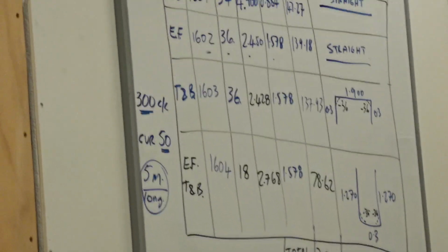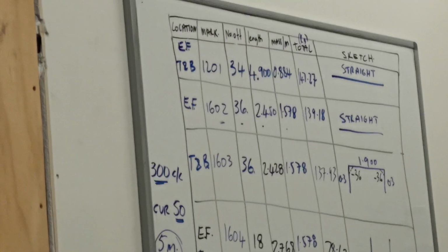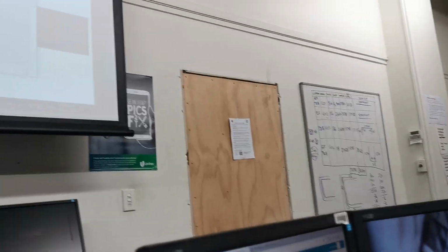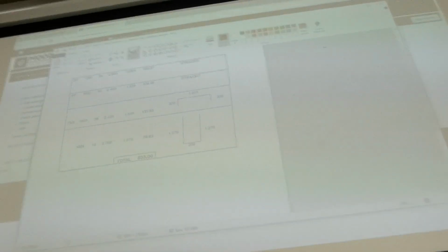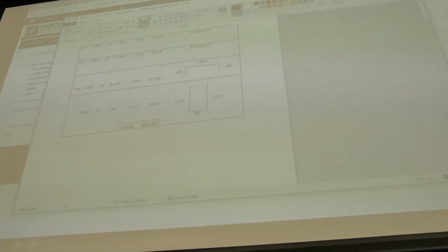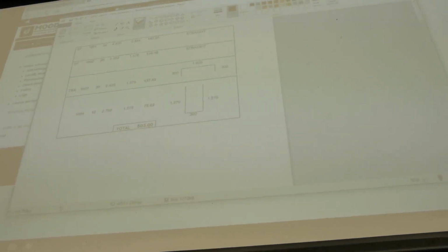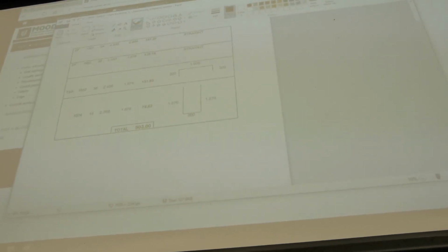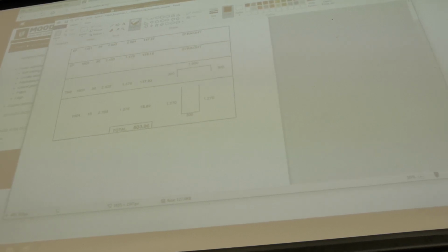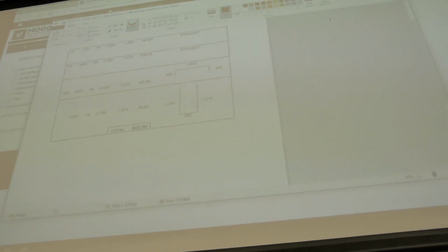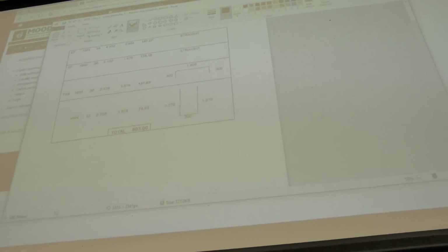When we label our bar marks, we start from the bottom of the structure normally. This one here is a bit different. We've gone from kind of the top to the bottom. It's only one structure and 4 bars. But if it's a multi-storey building, we tend to start with the lower numbers on the bottom floor and work our way up. So when they stack the bars, they can find them easily for each level. So if you really want to annoy the steelfixer, you make the numbers all wrong on a building and they can't find them, and it really upsets his way of putting everything together.